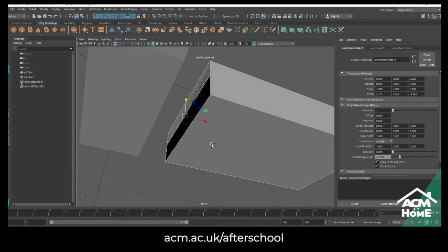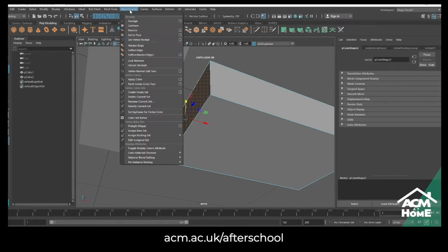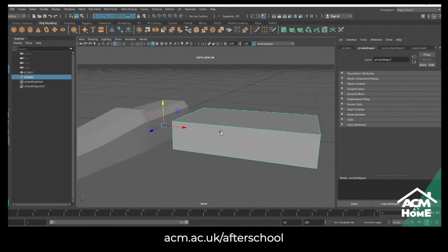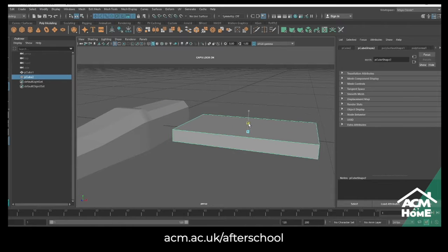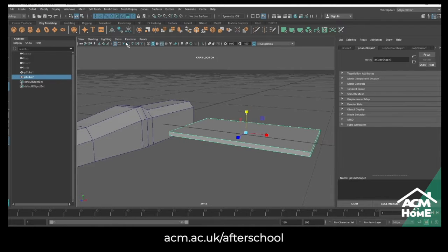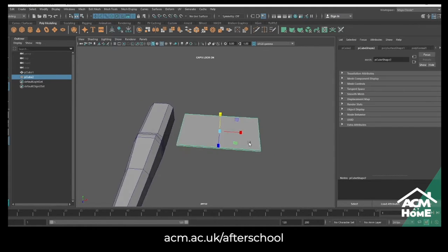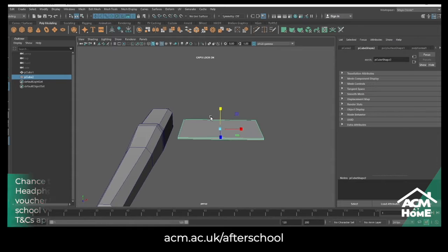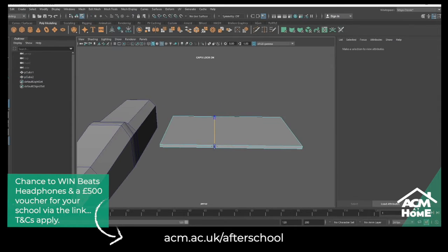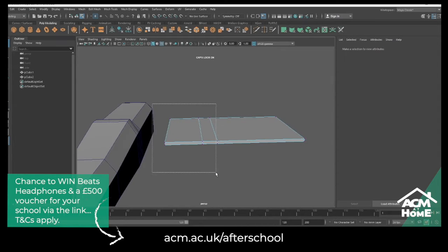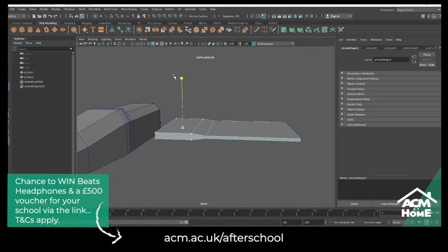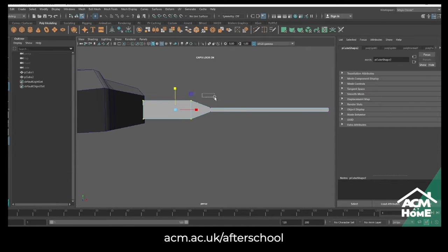Similarly here, in order to speed up time, rather than make a whole new primitive, I just cloned the original one and took a section that I wanted from it and began modifying that. So I turned on the wireframe on shaded and turned off the grid system because it was getting in the way. Wireframe on shaded basically acts as a wireframe guide on top of the actual model. That helps you get an idea of the structure, where to edit, and things to pull around.